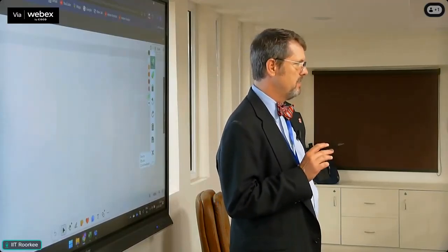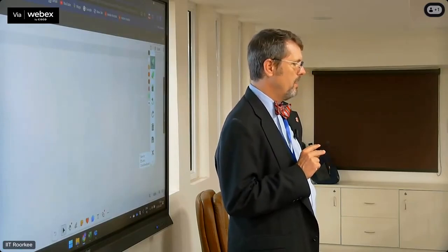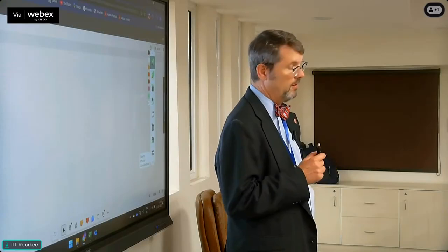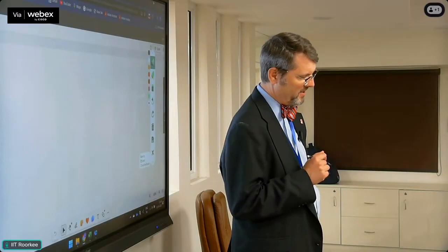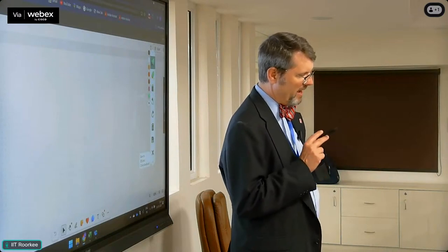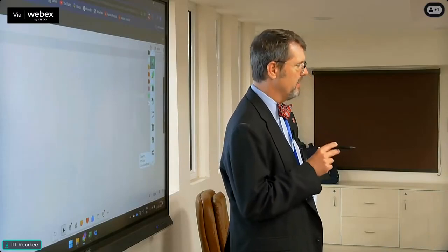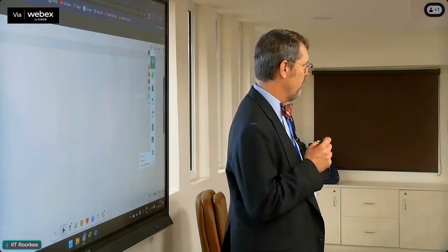Okay. There's a couple of different ways. One is you can calculate a runoff volume per a depth, but it's very simplistic. It's all based on impervious surface. The second one is based on curve number. And I tell you what I'm going to do: I will go through that when we talk about wetlands on Wednesday. It'll be a very germane calculation when we talk about wetlands on Wednesday.